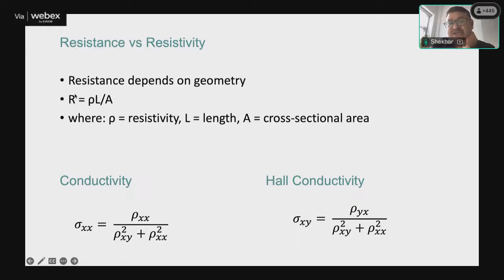We read the resistance of any kind of solid material. It doesn't matter whether it is magnetic, non-magnetic, insulating, or conducting. Then we have a perfect geometry, where we measure the length between the probes and the area of the cross section of the sample. Then we calculate the resistivity.